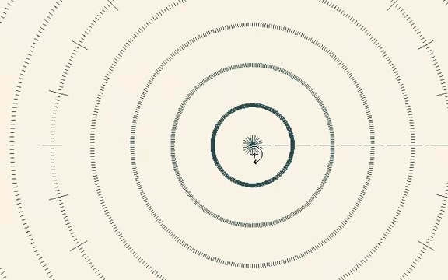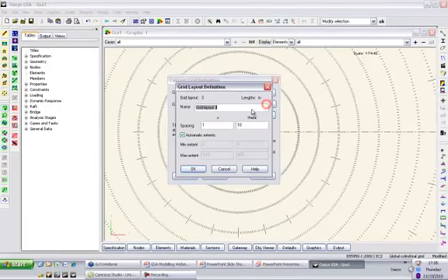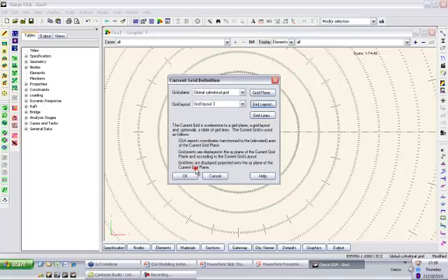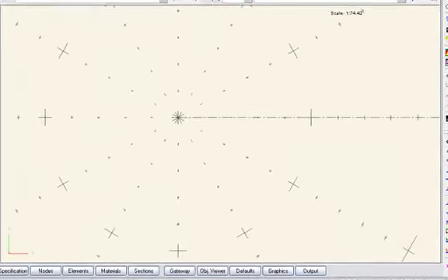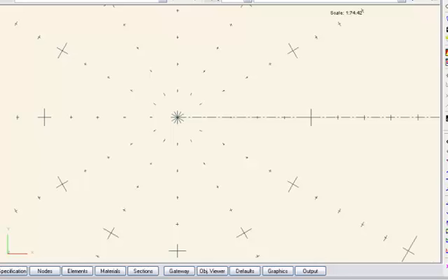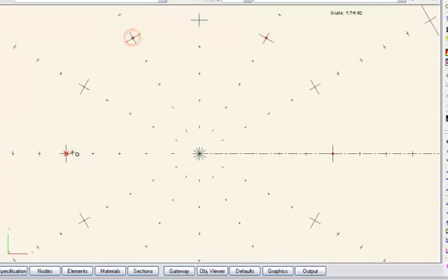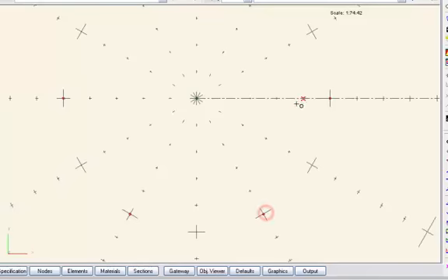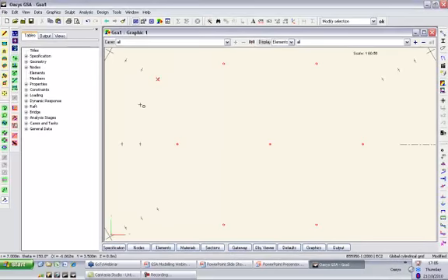Which you can define yourself and snap to. Now, these grid points. Let me set these a bit further apart. Let me say 30-degree centers. You can use these for drawing in nodes. Let's just draw in some nodes using the Add Nodes tool, and so on.